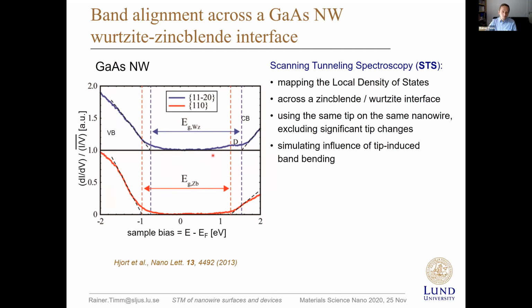We see even some dopant contributions here. And then when we go towards positive bias, we are tunneling electrons from the tip into the empty states of the sample. So we are probing the density of states of the conduction band. And in STM or scanning tunneling spectroscopy experiments, the Fermi level is always positioned exactly at 0 bias.